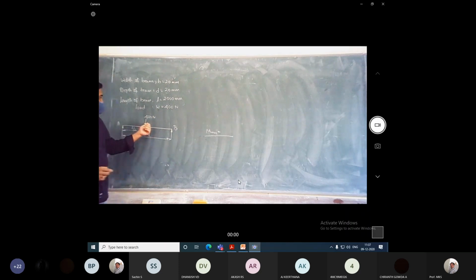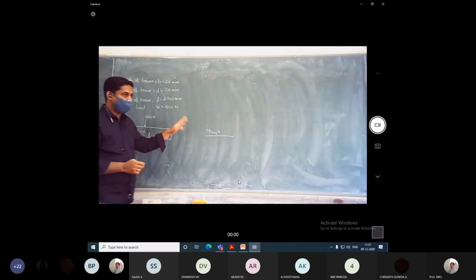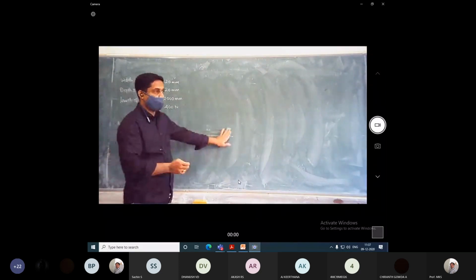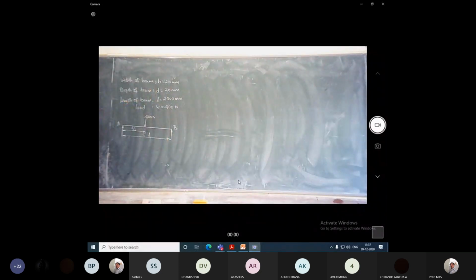So what is the maximum moment for a point load? Somebody has written it, and if you turn your page, you can find it. What is the derivation we have done? So maximum moment M max, or you can look at the moment diagram. In the moment diagram, it will be represented. It is WL by 4 for point load at the central point. So okay, we will just move on to this problem. Other parts will remain the same as the last problem.